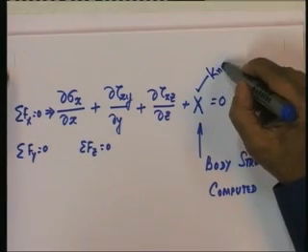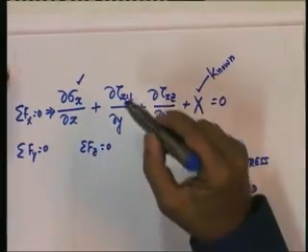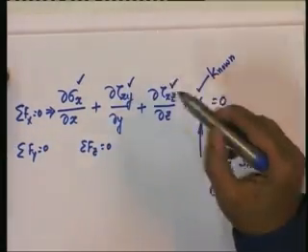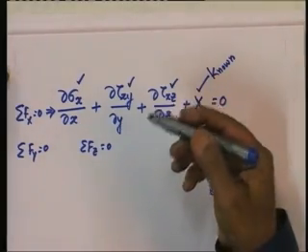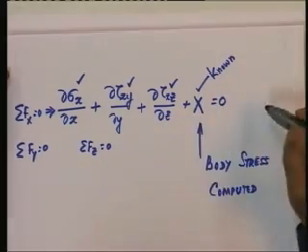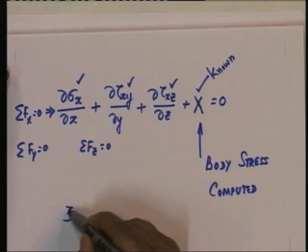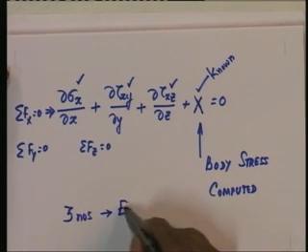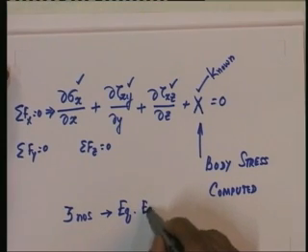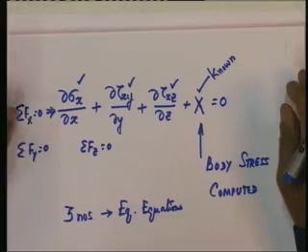which can be determined straight away without the use of even theory of elasticity, and therefore, this is a known quantity. What are not known are this stress sigma x, this stress tau x y, this tau x z. Similarly, the other stresses sigma y, sigma z and other shear stresses. One set of equations, that is 3 in number, for equilibrium equations are the first set of equations that we shall be considering in theory of elasticity.